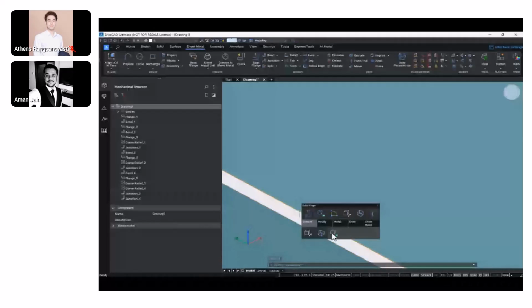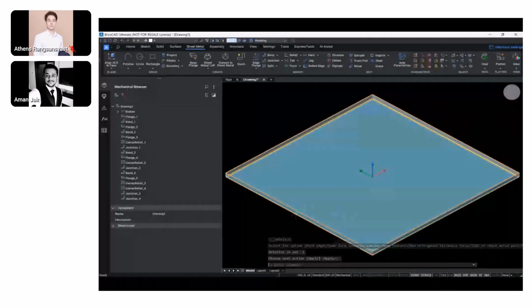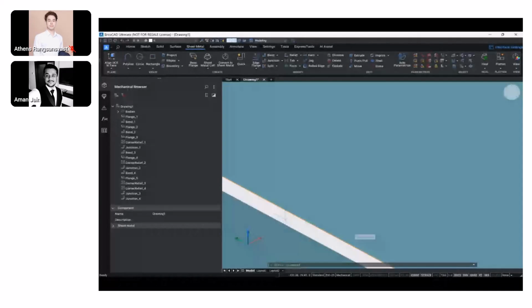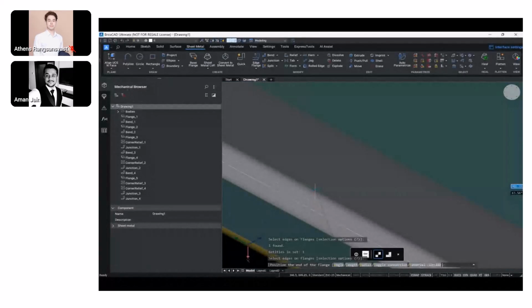So we'll try to create one more flange body. Now this is actually the door of the sheet metal enclosure that we are trying to create or model. And hence we'll be creating one more outside flange with a distance of 10 mm and a 90-degree bend angle.